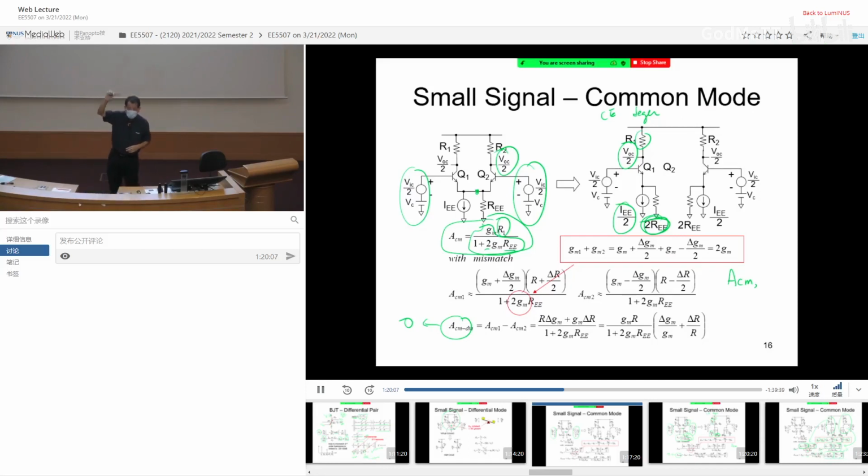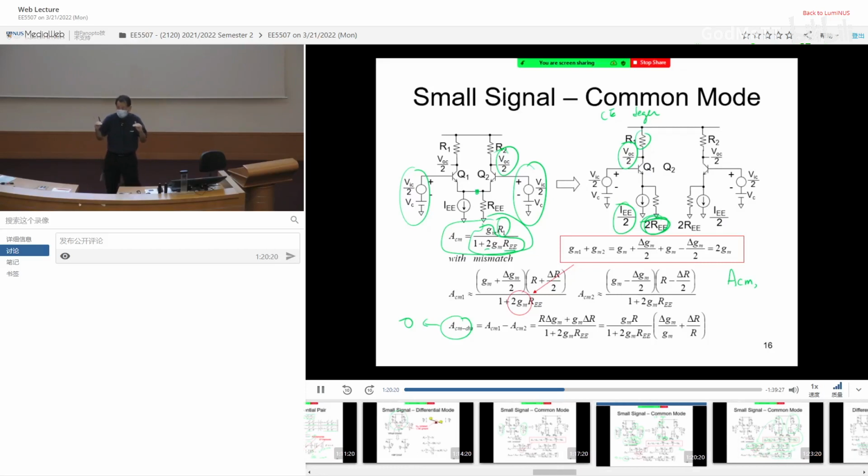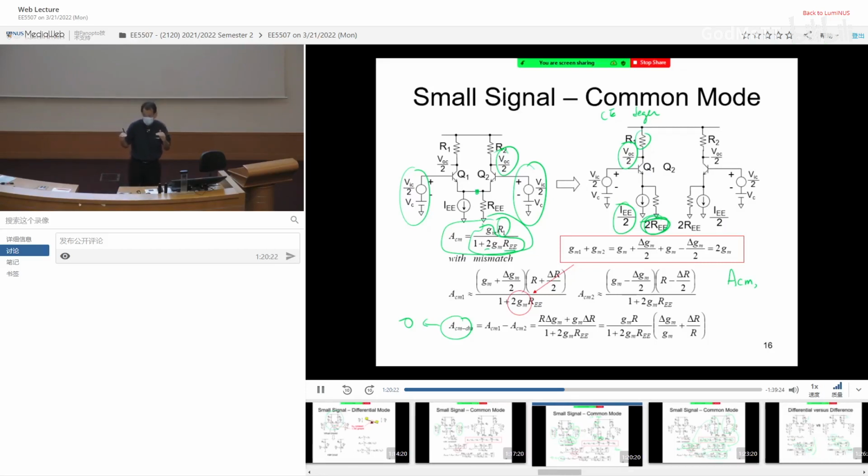If we talk about power noise, very likely the power noise will appear at the two inputs in the same manner. Am I right? So the power noise will actually appear as a common mode signal to the two differential inputs. So if the power noise moves together, you look at the output also move together, but you take the difference, 0. So the effect of power noise on the differential circuit is 0. Right? So that is the beauty. Supply noise doesn't matter.